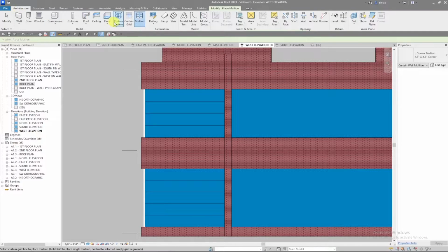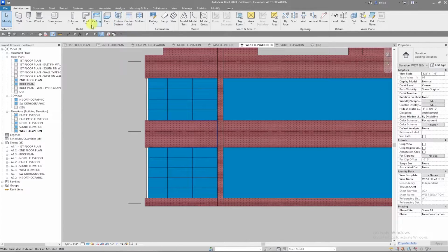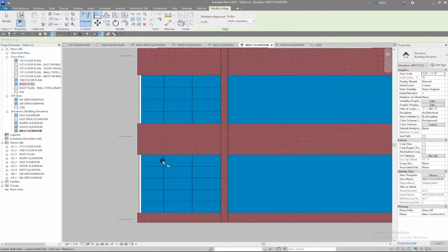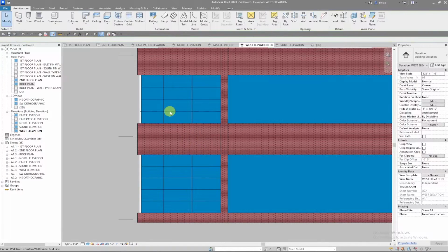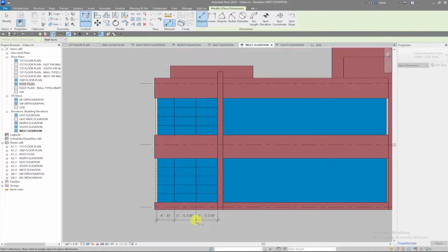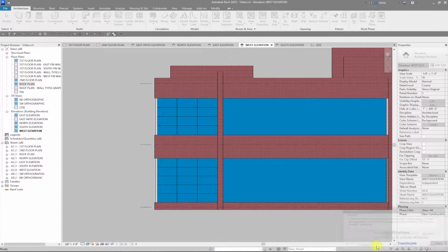So we can simply use architecture grid and place 2 verticals. Now again, just to get these in the right spot for now, I'm going to go from the face to these. Actually, before I do that, let's align these and lock them so that if I dimension 1, they should all go together. So we'll dimension these, but just like before, we're going to delete the dimension immediately afterwards and unconstrain them, because we are going to dimension these on the plan, and we don't want those dimensions, those constraints, to interfere with each other. So I'm going to hit the equals just to get them in the right spot, hit escape, select the dimension, delete, and say unconstrain.